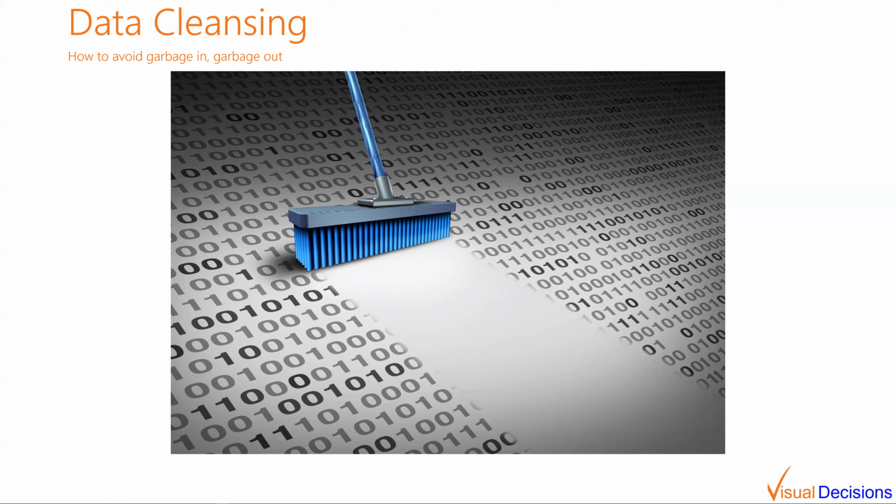As much of the data that you can collect automatically, obviously it's good to do so, but the fault codes that you're getting from machines are really the symptom of what's happening as opposed to the root cause. So you need to collect those process variables, what's happening in the machine during the process, whether that's pressures or temperatures or vibration or noise or anything along those lines. And then you also need to be able to collect the data as the process is occurring.